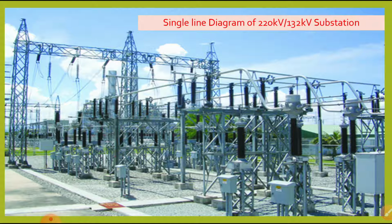A substation may include transformers to change the voltage levels between high transmission voltage, where we require to step up the voltage to reduce the line losses, and lower distribution voltages, or at the interconnection of two different transmission voltages we also require a substation.